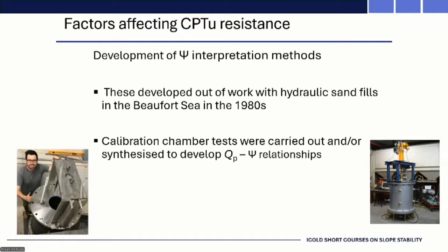But you need tens and tens of kilograms of material. It takes maybe 2 days, if not more, to set up a sample and troubleshoot all the leaks, and then the test takes 15 seconds. Then you pull out the cone and have to take all that material out again. Can you dry it and reuse it? We think so, because you're shearing a very small volume. But it's a really painful process.